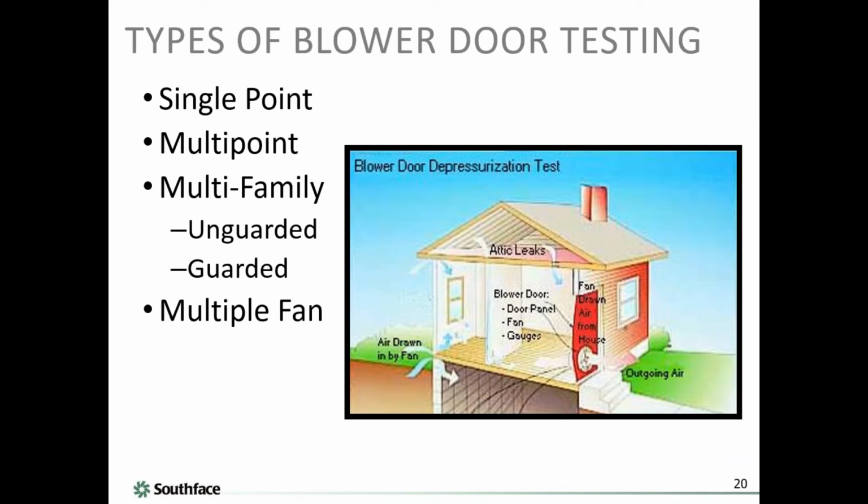As we talked about, how important it is to actually go back and verify the improvements were done correctly. And then ventilation, a whole other interesting topic. It is a gross assumption to assume that because it's a commercial building, they are meeting commercial ventilation requirements. We've seen them underventilated and have huge humidity issues, overventilated and have comfort problems and energy problems, and humidity issues. So ventilation is a whole other fun topic.